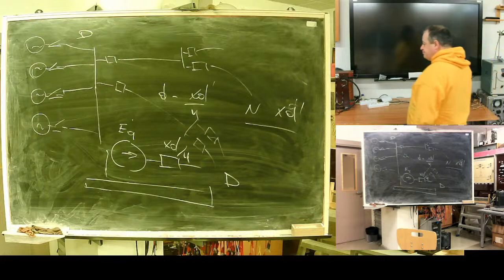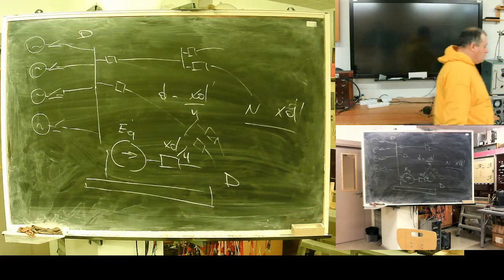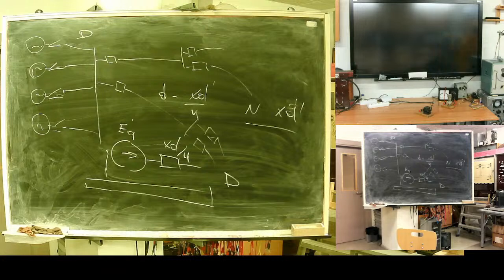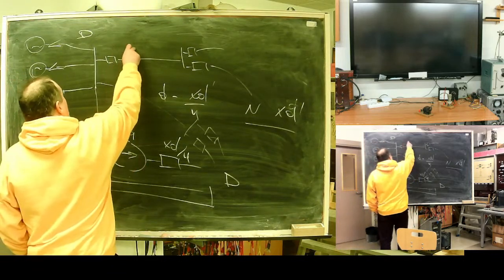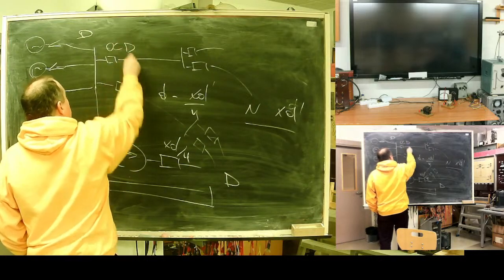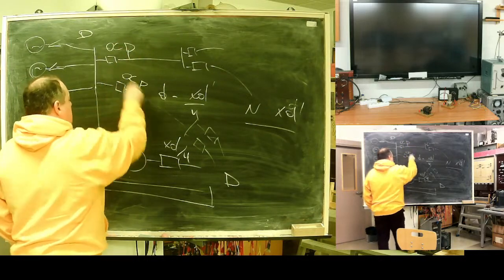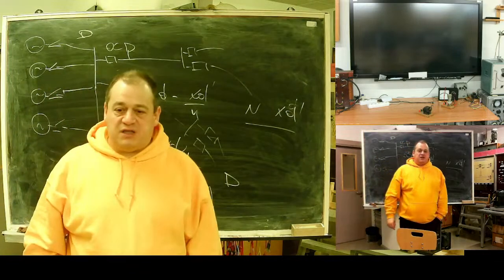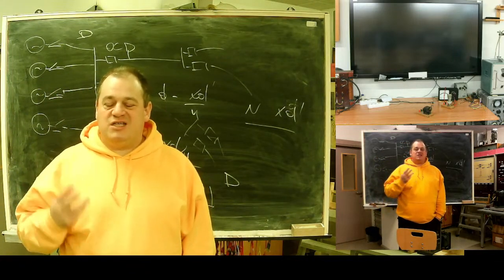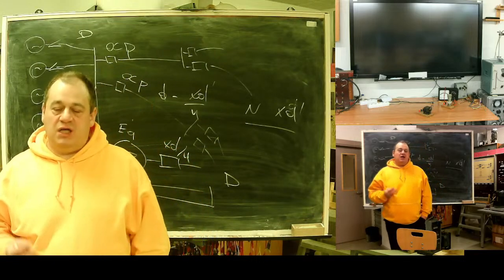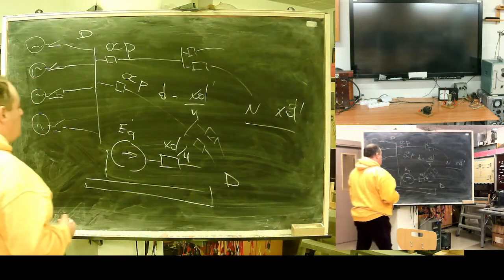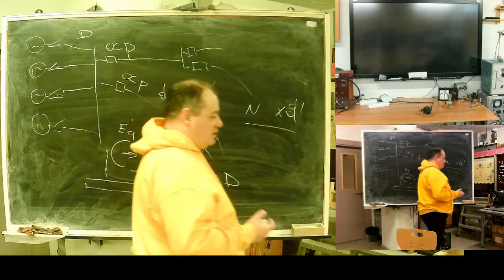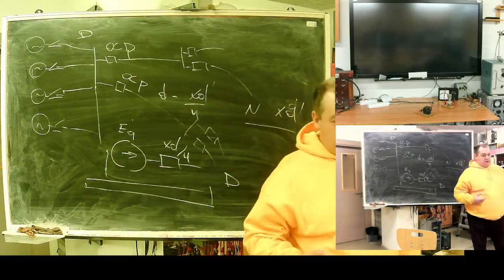Meaning what? I call it a significant change in the fault current. This means that for the overcurrent protection I will have here, all around, I will need to change settings for overcurrent protection at least twice a day, and do it really all over the network.